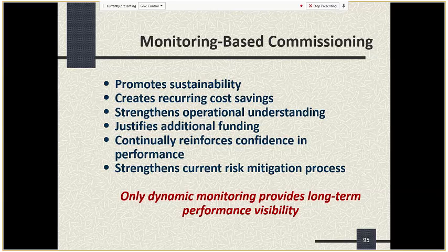Monitoring-based commissioning allows you to take your performance data and direct your efforts at tuning the system. And especially, this is less true in Hawaii, but it's not completely untrue. You guys are famous for having the world's best weather, but you do have seasons where there is slight variation in things like the level of rainfall, right? At least that's been my experience, that rain can vary during different periods of the year, and that may require you to do at least some modest amount of seasonal tuning of your chillers, because the loads they face may be different.